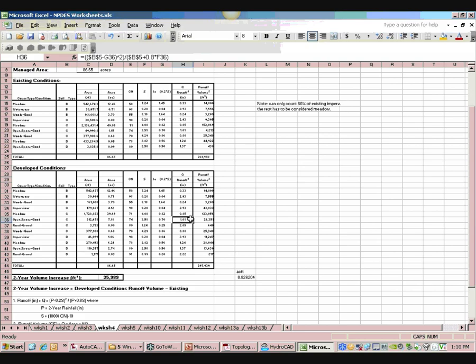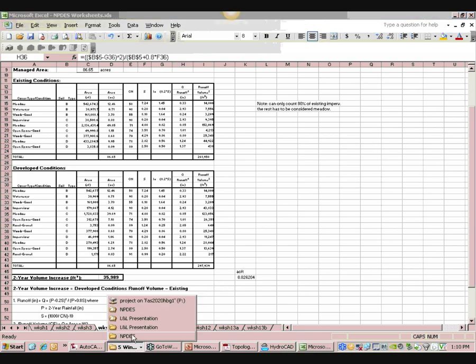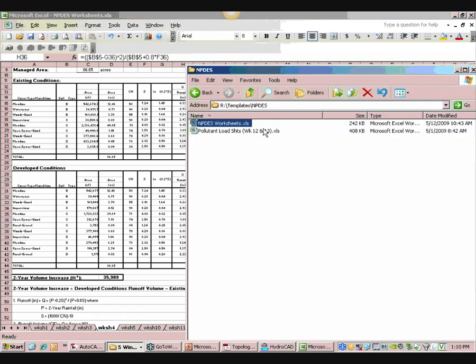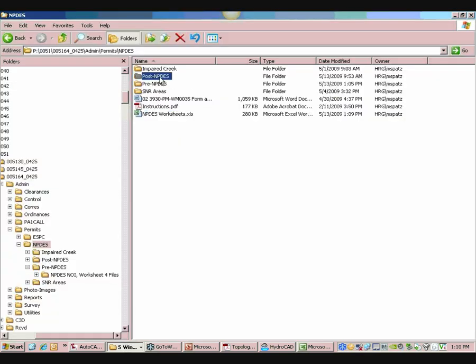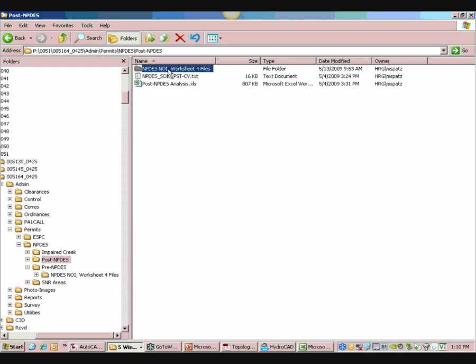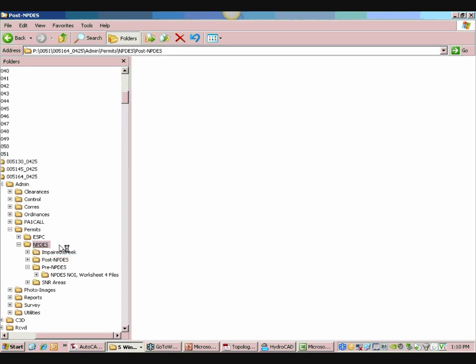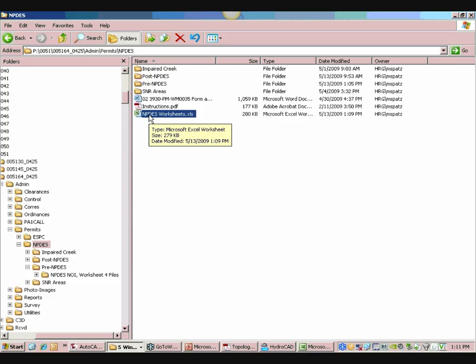Yeah. So doing it the right way, you just run those topologies, a couple minutes, paste the data in, hit update worksheets. I go back to here. I paste the data back into these two Excel files, hit the button, it updates this sheet, which since my NPDES calc sheet is linked to that, it automatically updates that. Next time I open it, it's right. So that investment up front can really give you a lot of gain on the backside when you have to update stuff. And since Stormwater is so iterative, it's important that we streamline that process for our updates.